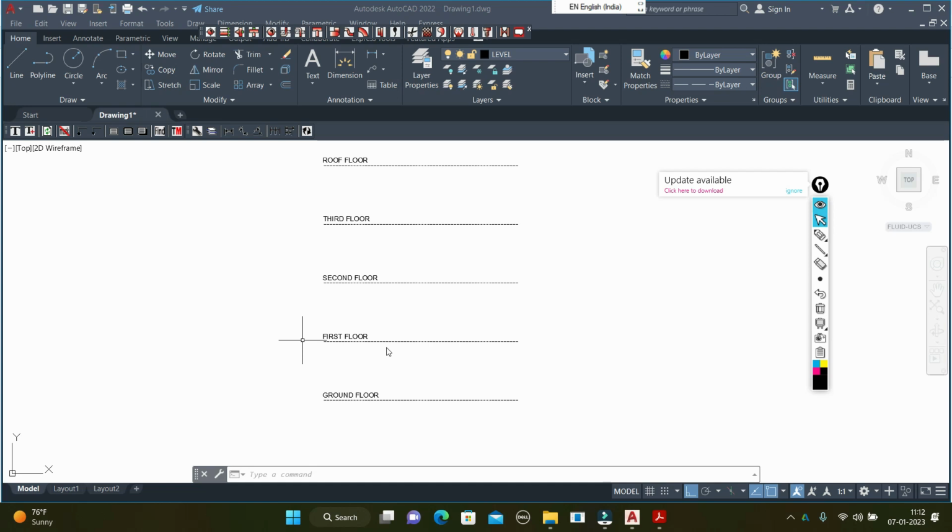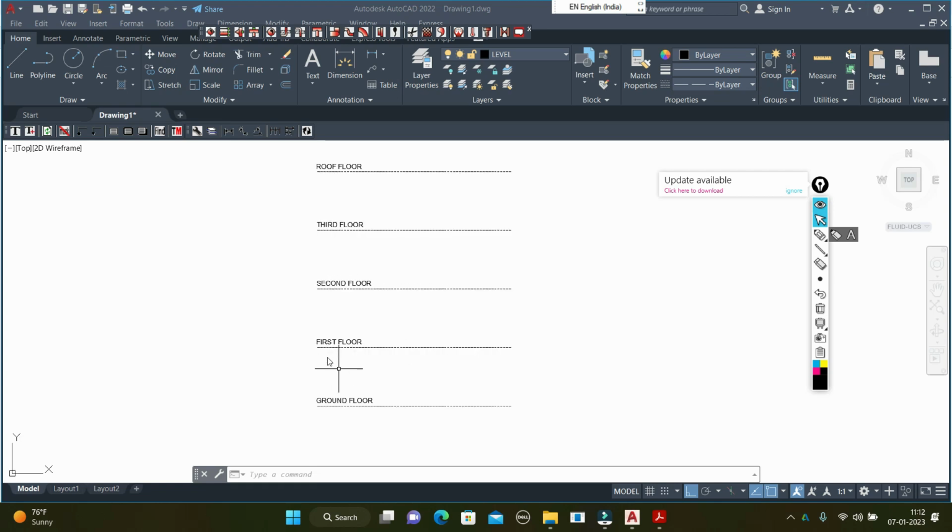How to decide hazards? If you have not watched my hazards video, then kindly go and watch that video so that it will be clear about the hazards. Okay, so here suppose this building and this floor exceeds 52,000 square feet. So we have to take two risers.